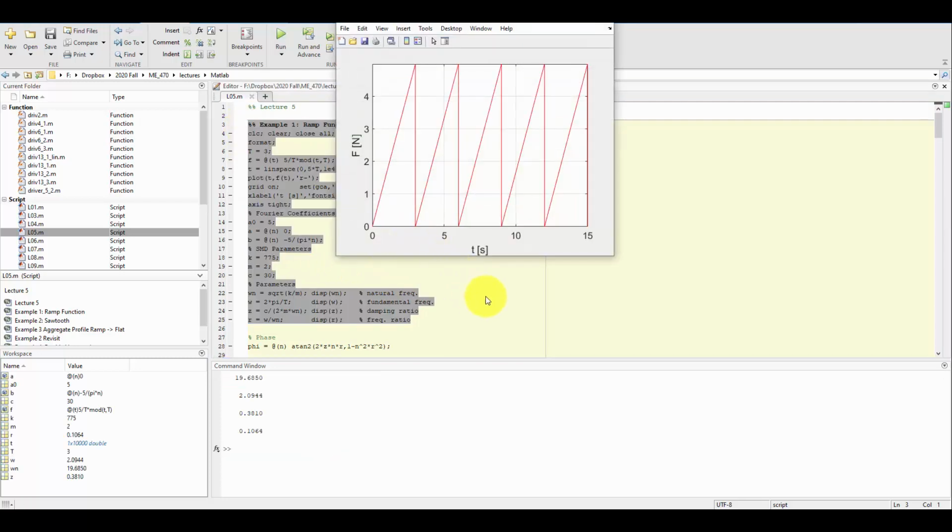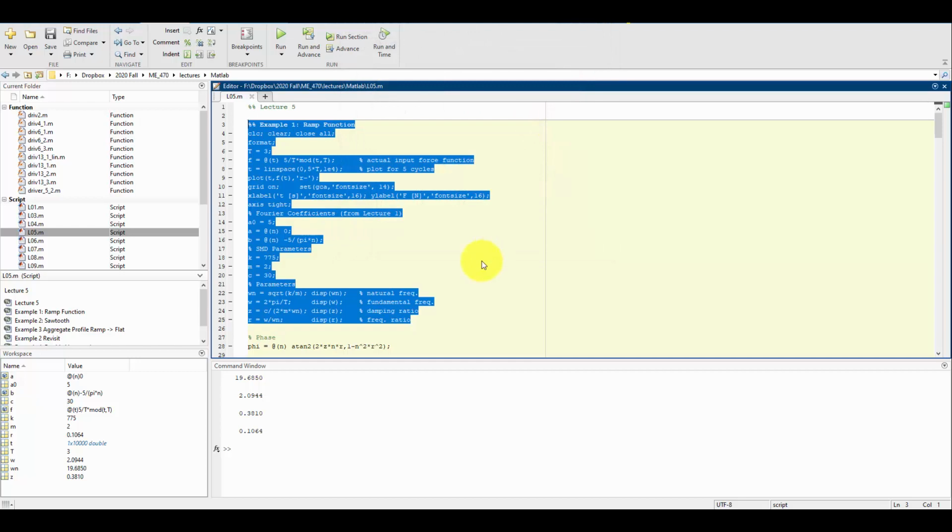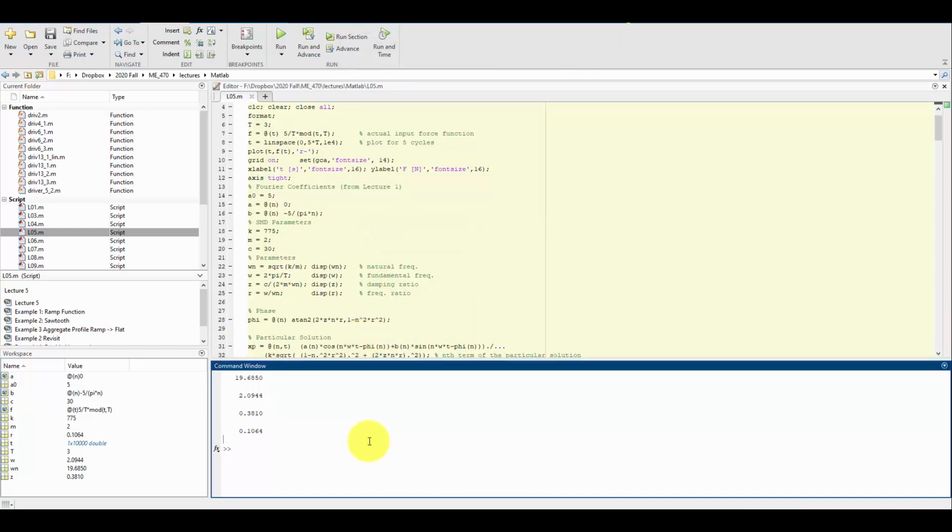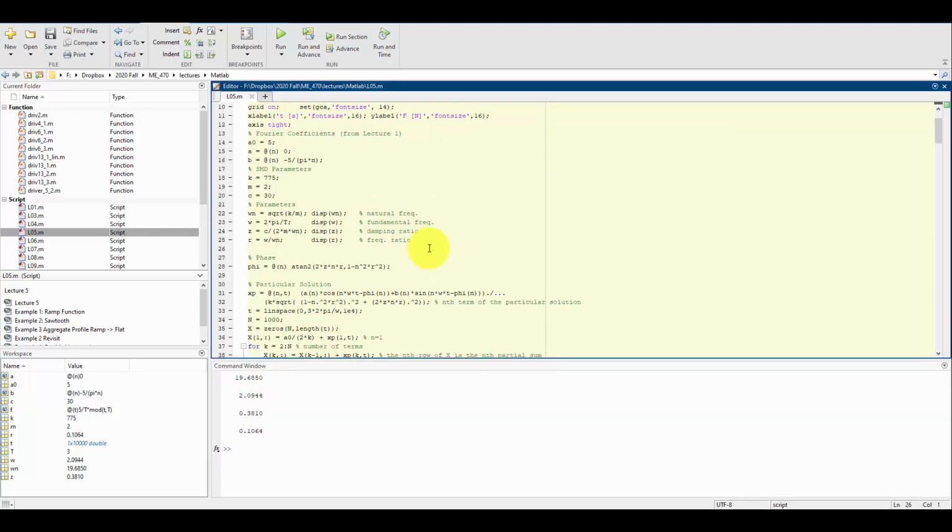and get some values. That's what the plot looks like of the forcing. And just to recap, so this is the R that we get, 0.106 for about, and then some of these other calculations are zeta value, our fundamental frequency, which was 2/3 pi, about 2.09, and the natural frequency. So these other things, I'm not going to try to calculate them out by hand, but I can define phi as a function of n. This is coming right from what I wrote by hand and also what's coming off the slides. So for any value of n, I can now calculate what the phi value is for that n.